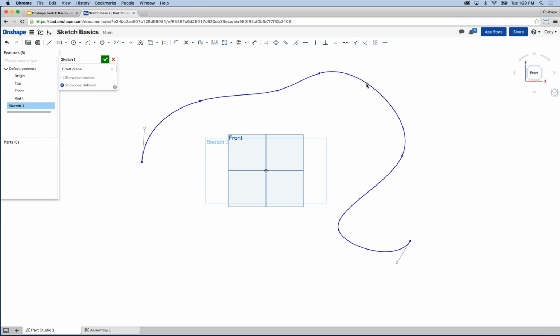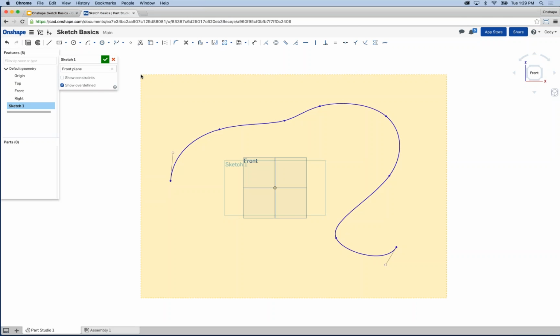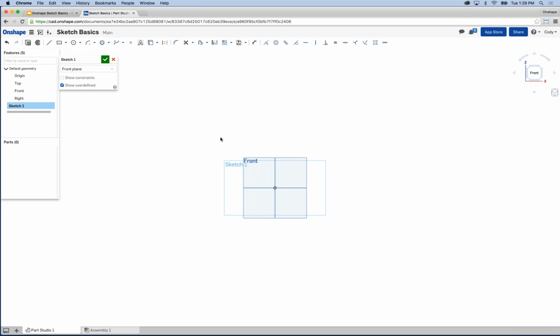Okay. So again, you're not forced to create the spline perfectly when you're sketching it. Just construct it roughly and then use the various points and handles to really constrain its shape, to define its shape. So that's a few tips on splines. Let's get out of that.